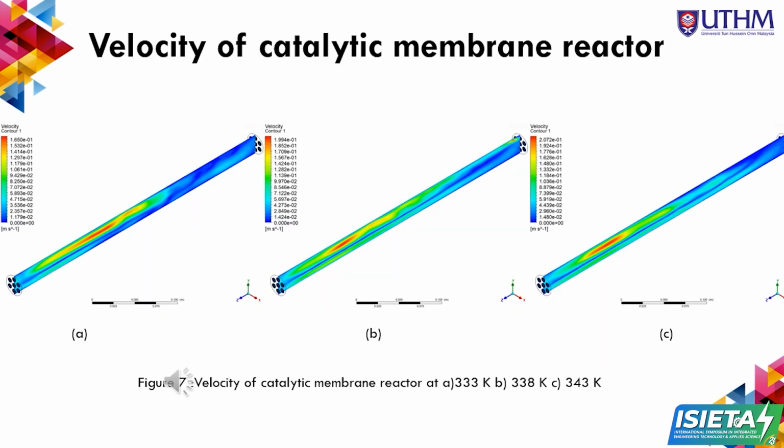Based on the CFD simulation, the velocity vector colored by the volume fraction of glycerol within the reactor. The computations began with the laminar model with the liquid at rest to predict the system's hydrodynamic behavior in the turbulent regime. The k and epsilon fields were initialized. The turbulence model was initiated after the liquid velocity in most reactor areas was greater than 0.